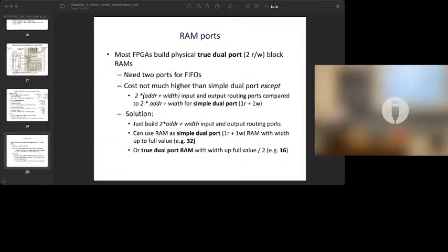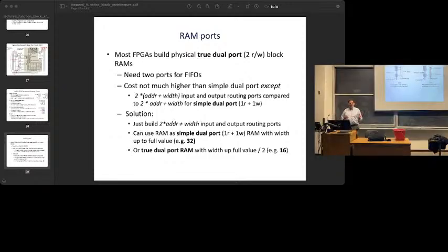Yeah, so that's a great answer. I'm just going to repeat that. So what I've shown you is kind of a straightforward way to do this, but it's not the smartest way to do it. It would give me the ability to turn every individual LUT into a RAM. But that's probably overkill. Not that many people need such tiny RAMs. I can instead think about turning a whole logic block into a RAM. And if I do that, I can basically share the write address signals. I can say, well, I'll write to the same location in every single LUT based on this write address. And so it's another example of how a logic block can help you by creating a hierarchy where you can share signals. And that's exactly what they do.